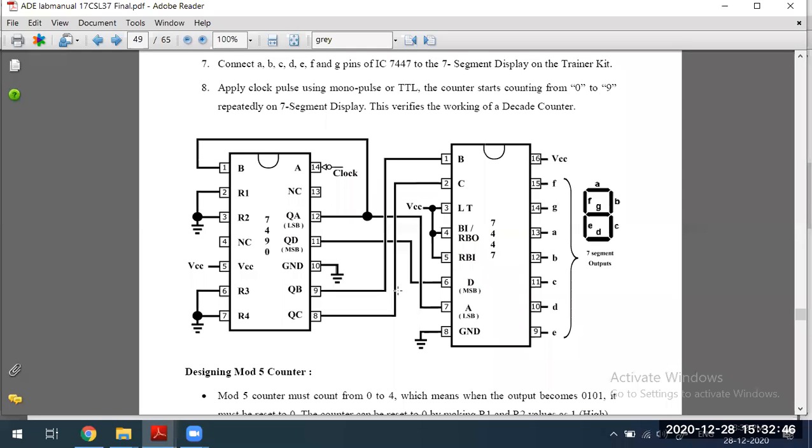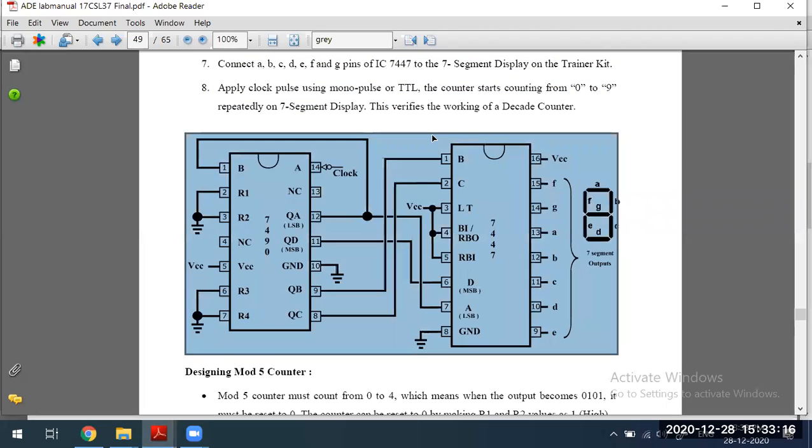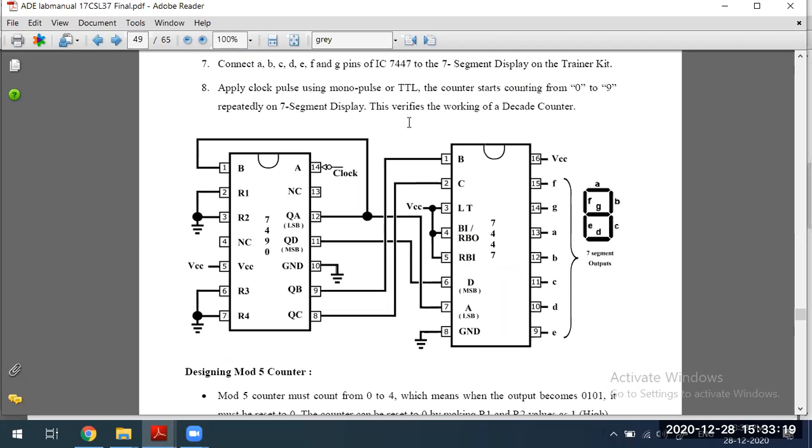Okay. Then the next question is why 2 ICs? The 2 ICs are, in order to connect to the 7 segment display, in order to drive this 7 segment display, 1 IC. In this 7 segment display, for 7, ABC should be on, for 8 everything should be on, for 2 only some of the displays should be on. Which one knows this? This IC knows, 7447. 7447 is a 7 segment display IC.